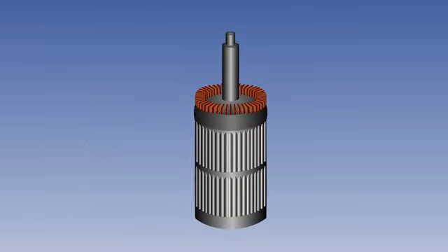Electrically driven gyros are powered by alternating current. If the power source is DC, then an inverter will convert DC to AC, as the gyro rotor consists of the actual armature of an AC motor. The gyro rotor is therefore an integral part of the electric motor.